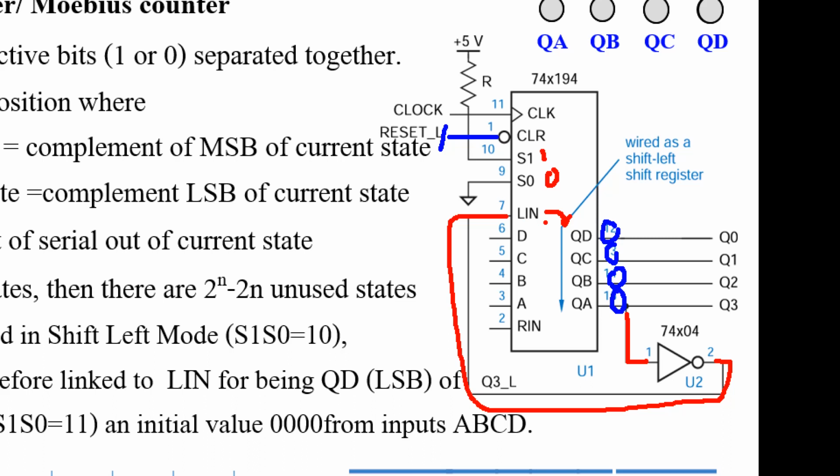Okay, now when the clock ticks, this at first is 0 right here, so this output is 1. So Rin is 1 now. When the clock ticks, this bit shifts down, this bit shifts down, this bit shifts down, or you copy these 3 bits down. Then it becomes 0, 0, 0, and Rin is placed to this. Then it becomes 0, 0, 0, 1.